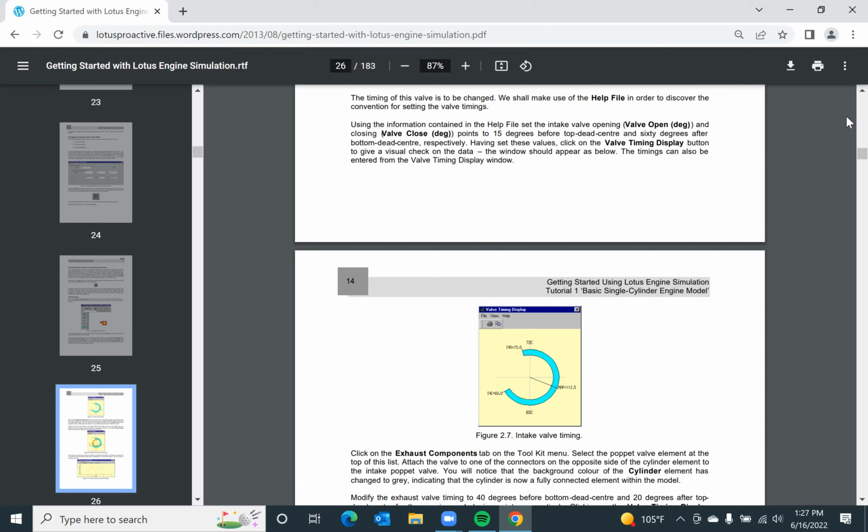So that's why VVT engines exist. The engine running at slow speed has different valve inertias, and the engine running at higher speeds has different valve inertias. That's why you have different valve opening and valve closing timings, just to make sure that those inertia effects are taken into consideration. That is what they call VVT technology.